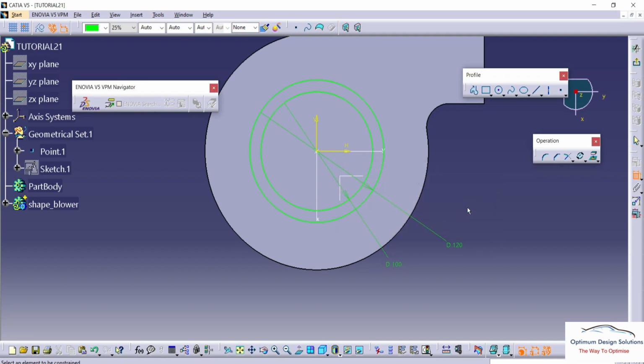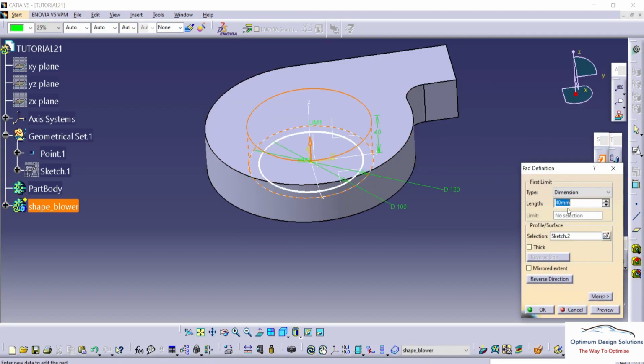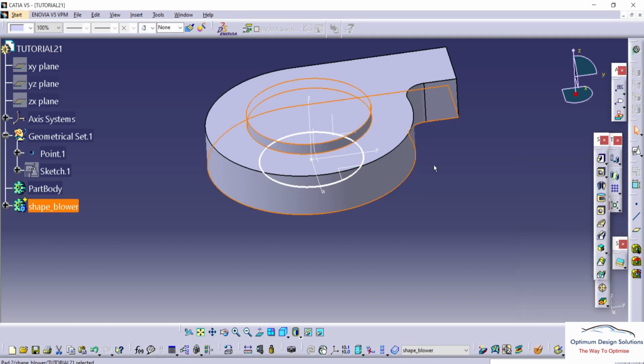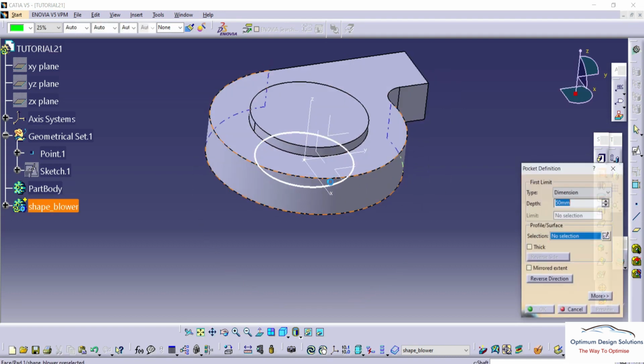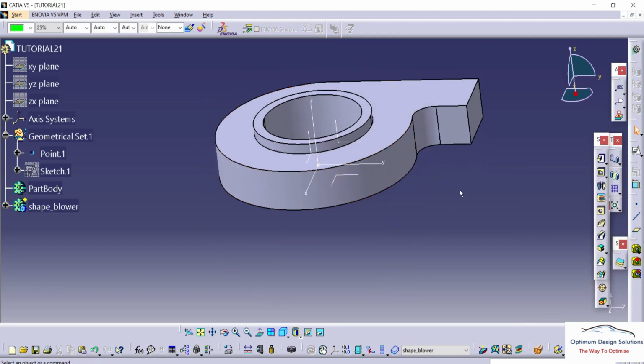Before that, we'll sketch this out. I'm saying that this cutout is used to suck the air. We'll pad this one for 55 mm. 55 mm is too much, we'll use 50 firstly. After that, if required, we'll increase it. So this cutout is total. We'll use the cutout command here. So this pocket is completed.